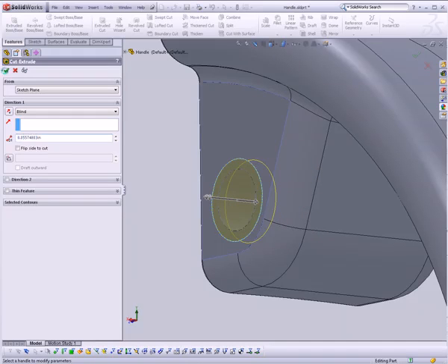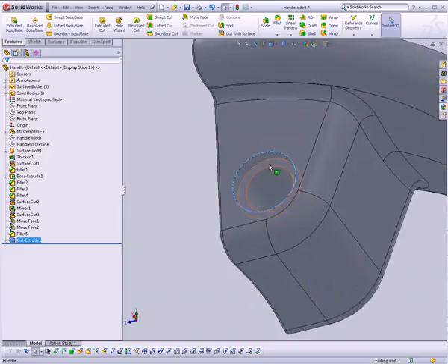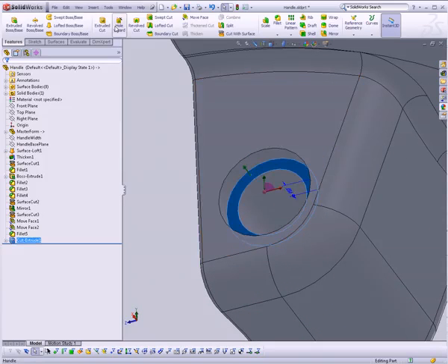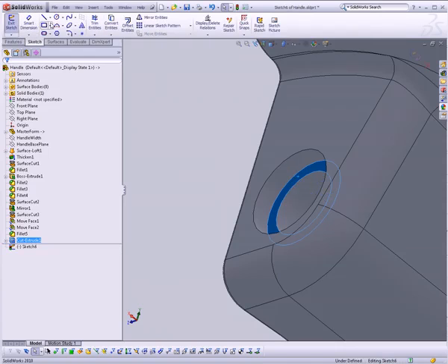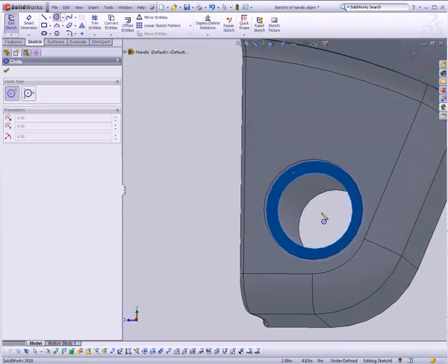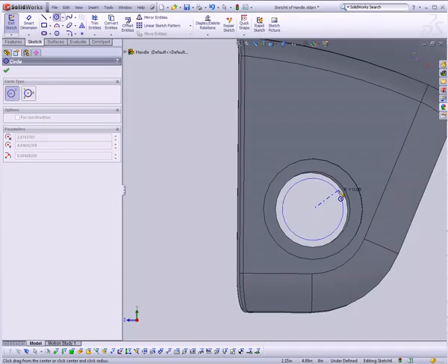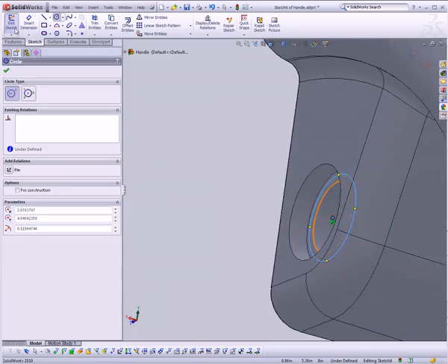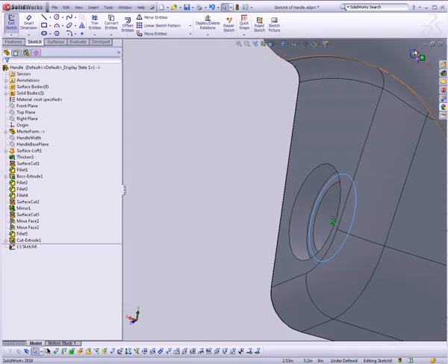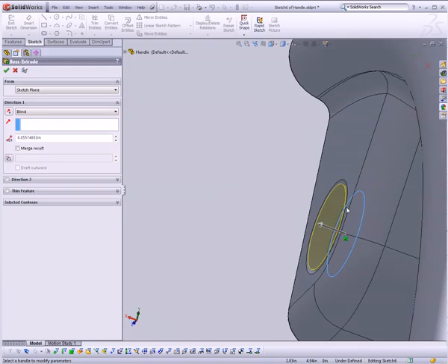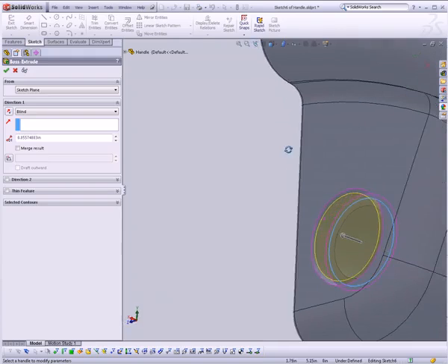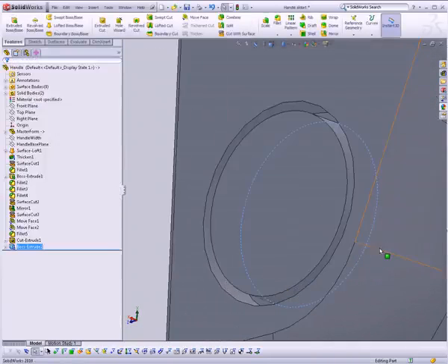And then I'm just going to add a screw, just right in here, just throw in a screw head, because otherwise it's just too much time. More time than we need to spend. So we'll just do an extruded boss, throw in a circle, right about there. And when I do this extruded boss, I want to make sure that I uncheck merge result, because I don't want it to actually boolean with the rest of this. I want it to remain a separate body so we can work with it separately and give it a separate material and all that kind of stuff.